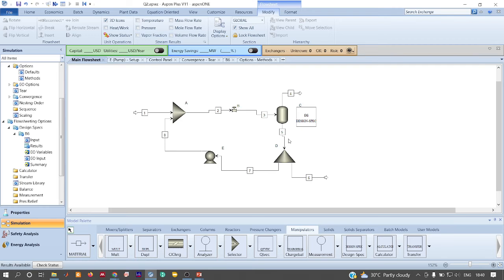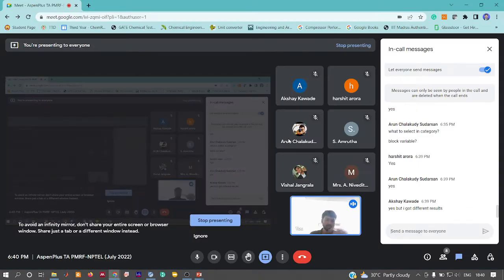If you want to do a MIMO system, then it becomes an optimization problem with respect to Aspen. There is no controller built in for a MIMO problem. Okay, it's only a seesaw problem. That's all. So could you follow the design spec? Okay, you got a different result. Just check the units in case you have mismatched them. That could be a possible reason.